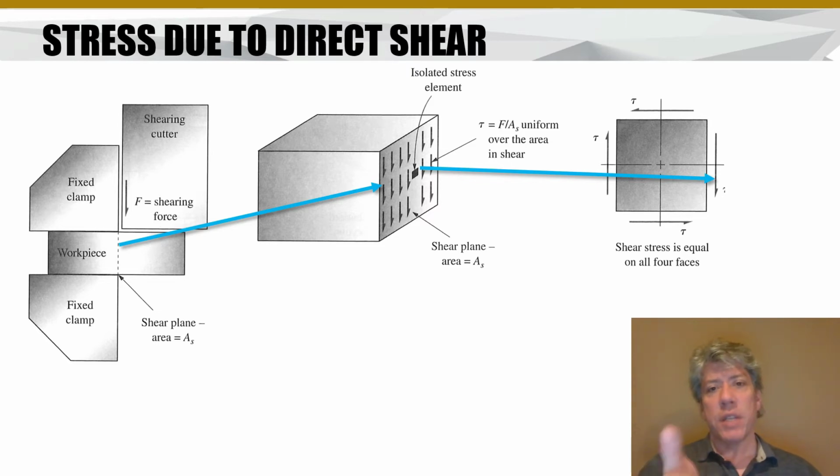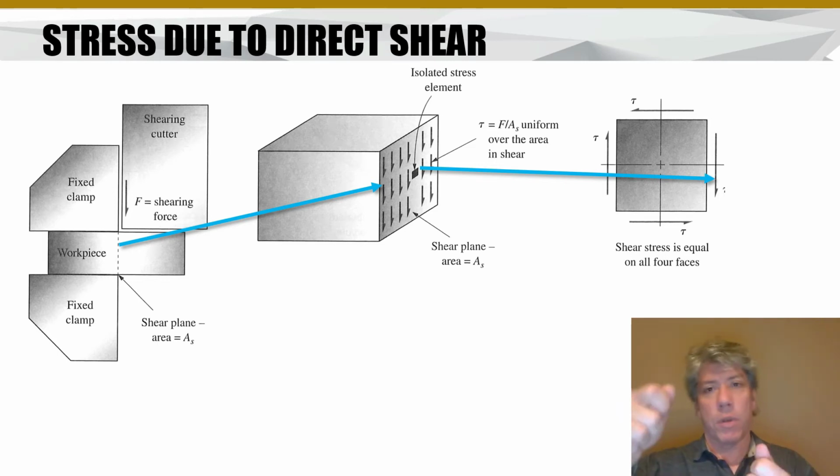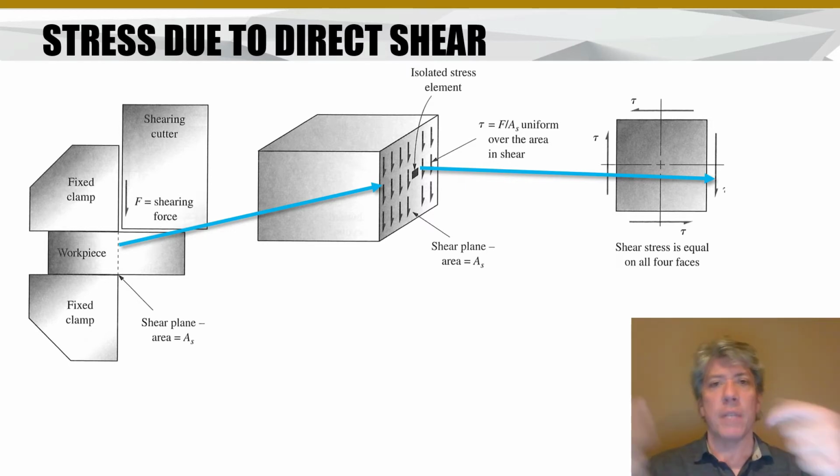That shear is a byproduct of the shear on the front face, right? That front face that we see exposed has shear pointing downward. We have to have shear pointing upward on the left-hand face in order to keep this cube from accelerating upward or downward, right? Well, but that causes a force couple, essentially, or I guess you could say a shear couple, that has to be counteracted by the upper and lower shears that counteract each other to prevent motion left and right, or acceleration left and right, and to also counter the tendency of the vertical shear stresses from rotating the element.